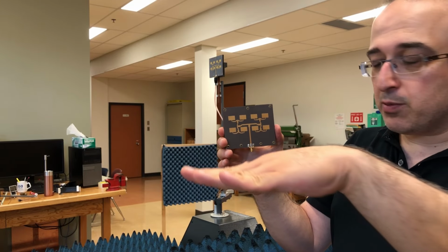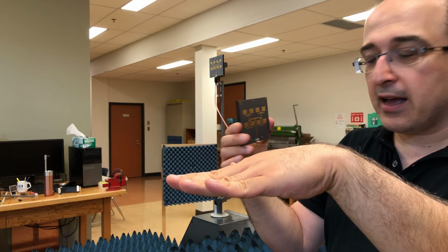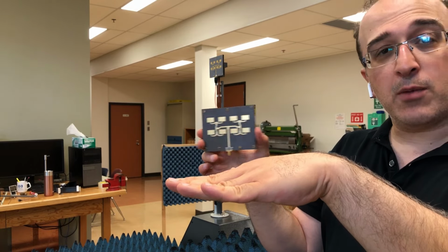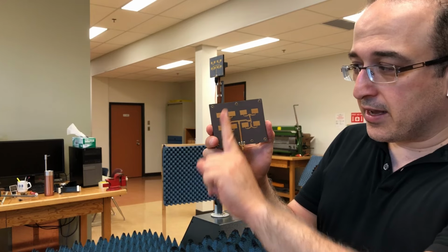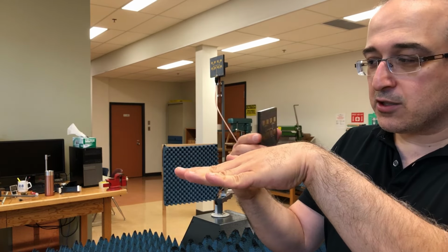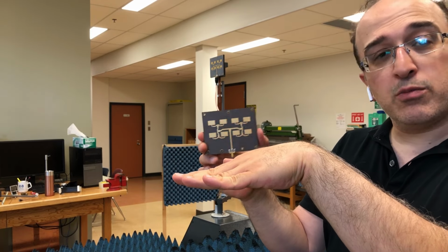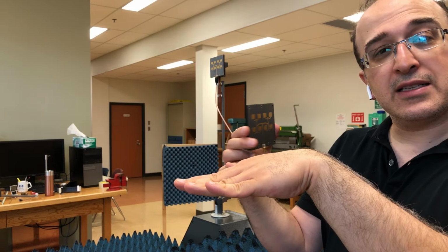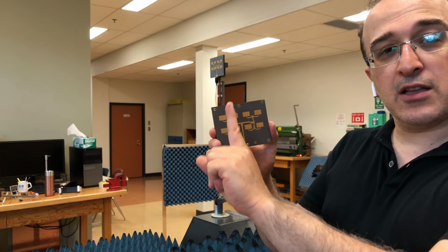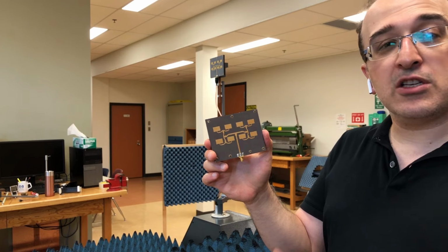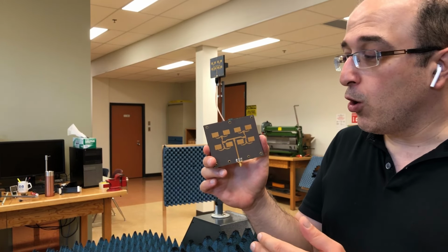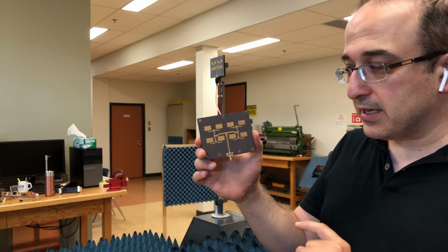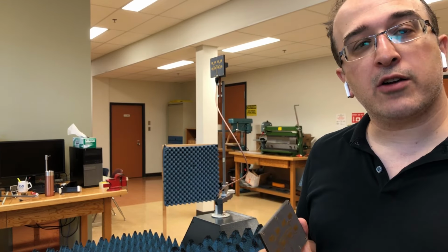So this is my H plane again, so if I start rotating the antenna like that, I'm measuring the H plane cut of this antenna. So that would be my H plane that I'm going to measure right now. But since our purpose here is to measure copole, we need to make sure that the transmitting antenna also has the same polarization as this. The electric field is like that, so you need to have a transmit antenna which is also vertically polarized, and our transmit antenna is our horn antenna. So we have a horn antenna which is vertically polarized, which is matched with this, and then we're rotating like that, and that would be our copole H plane.